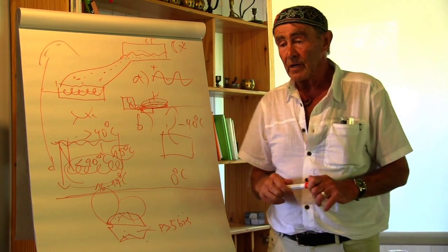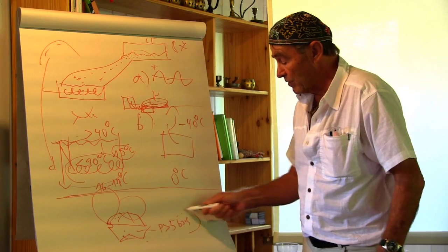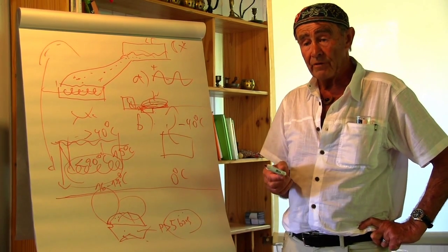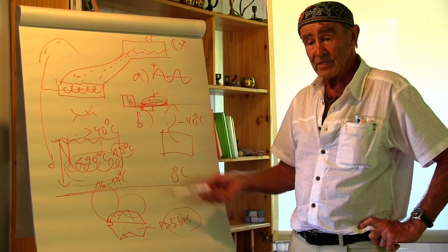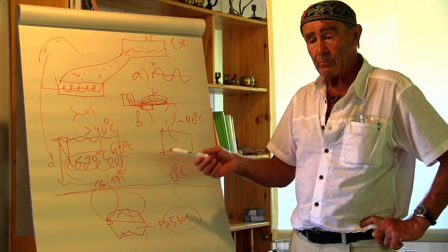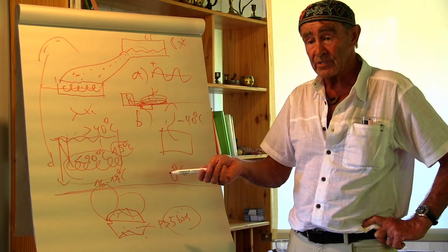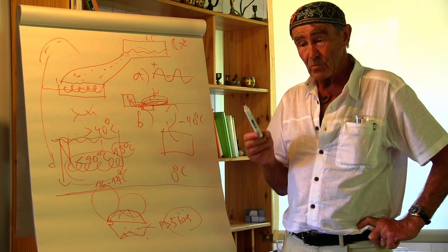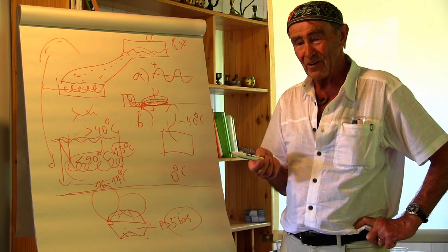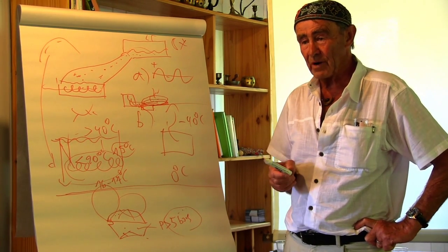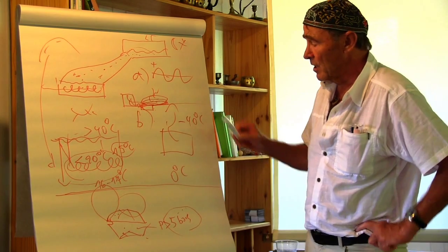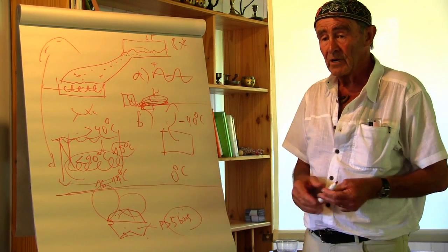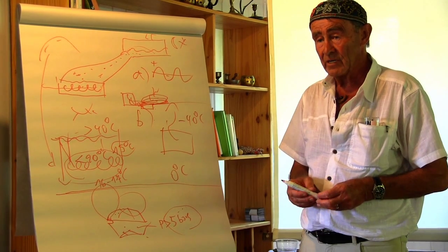So if, for example, we put 5 bars in, and we have 2.5 kilowatts, and then we triple the frequency from now 1.5 hertz to about 5 hertz, then we extract from the same engine 3 times 2.5 kilowatts. So we can play with all these parameters. So this is a pragmatic development of this engine.